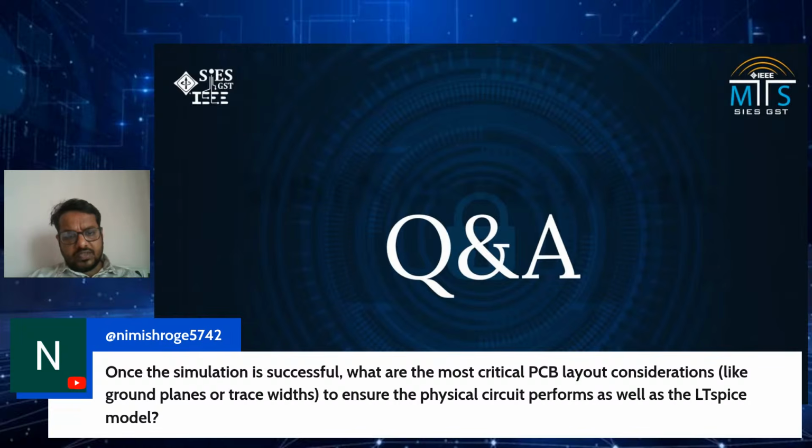Once the simulation is successful, what are the most critical PCB layout considerations, like ground planes and trace widths, to ensure the physical circuit performs as well as the LTspice model? Generally there are some hot traces, meaning the traces which will be carrying high frequency current or high frequency voltage waveforms. Generally high frequency current, and there will be nodes between which high frequency voltage will be appearing. We keep these traces as short as possible, because if you keep them longer, they will behave like a bigger antenna.